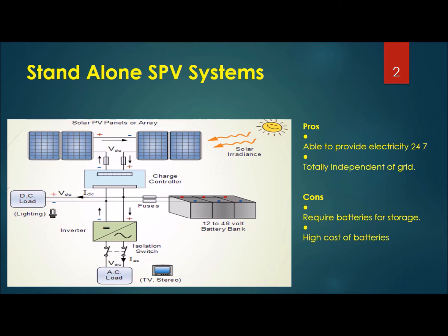Use of maximum power point tracking, also known as MPPT, using a DC to DC converter varies the output DC voltage due to varying MPP voltage because of varying photovoltaic cell temperature and solar irradiance. Variable DC link voltage across the photovoltaic inverter can affect the sensitive load supply.